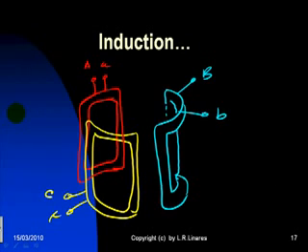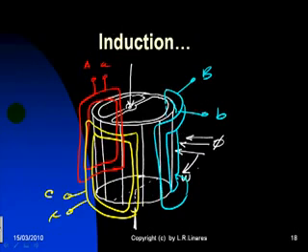Consider this scenario. The three stationary coils we've seen before, now in a 3D representation for phase A, phase B in blue, and phase C in yellow. If we apply a set of three-phase currents to those three coils, a rotating magnetic field will appear in the center of that setup. But now we bring a cylindrical setup with vertical wires like this one, joined at the top and at the bottom with metallic rings, and connected so that it's allowed to rotate around its vertical axis.